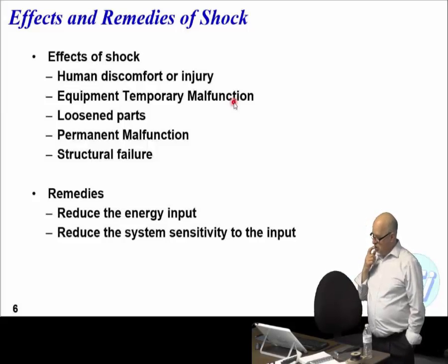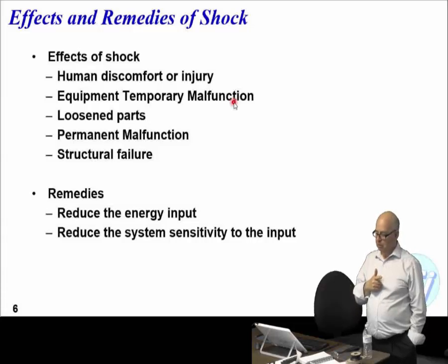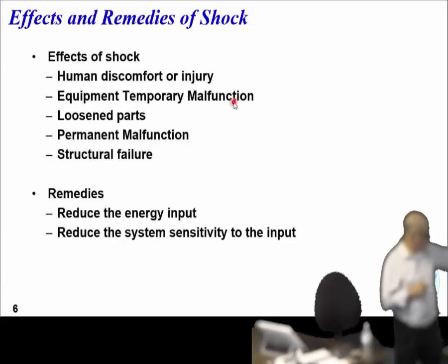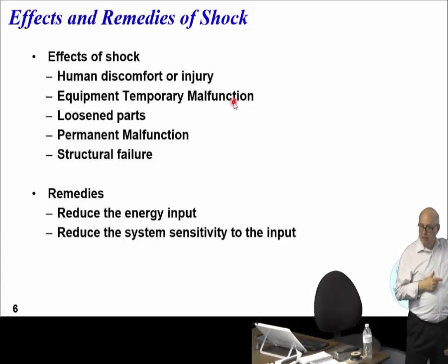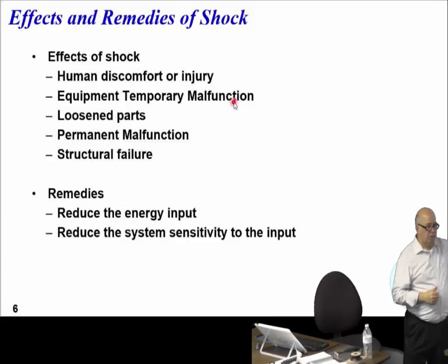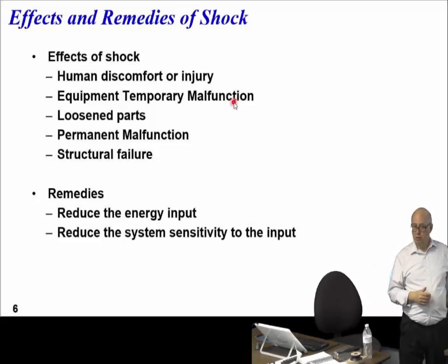Can we somehow reduce the energy going into the thing, or can we reduce its sensitivity to that input? This is looking at the design of the component itself, and making it shock tolerant, changing those switches to rotary from linear, stronger components where they like to get broken, thicker circuit boards, potting the circuit boards so that the components don't rattle. This one is saying, can we put in shock absorbers, packaging with space for shock? But really, that's all we can do. There's nothing else, because we can't usually control the shock.